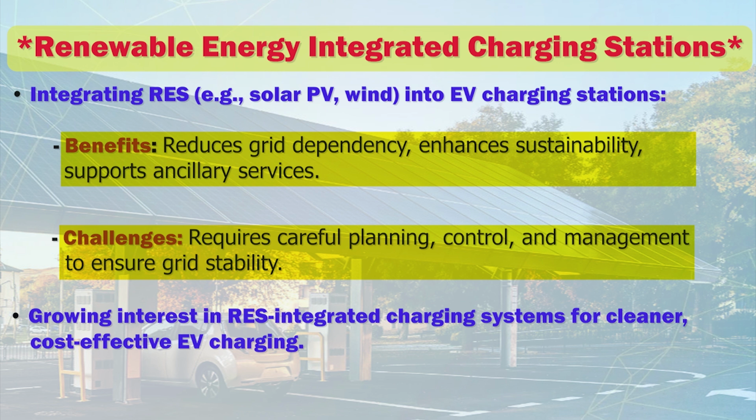But at that moment we need to control voltage and frequency at the point of common coupling. So, it could be a challenge whenever bulk power is going to be transferred to the grid. Under bulk power, we need to regulate these voltage and frequency parameters, I would say grid parameters, at the point of common coupling.